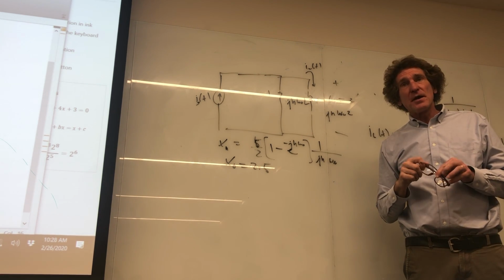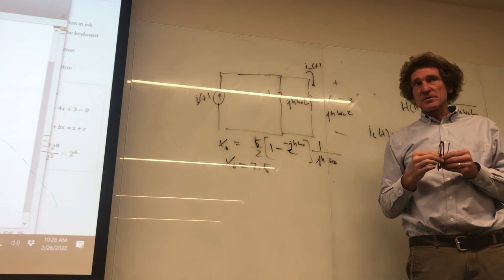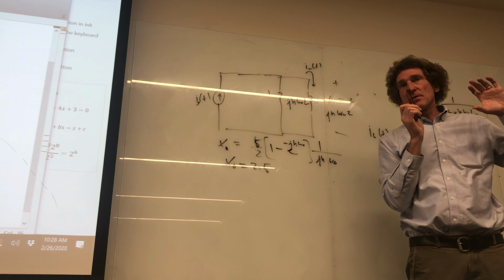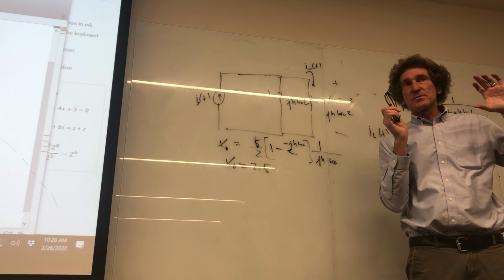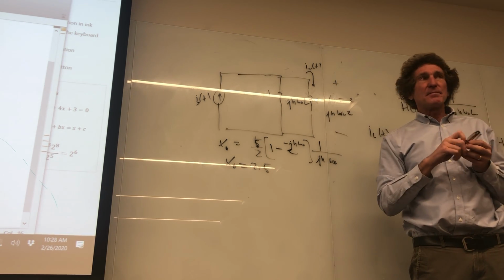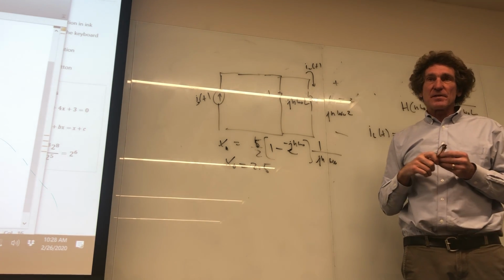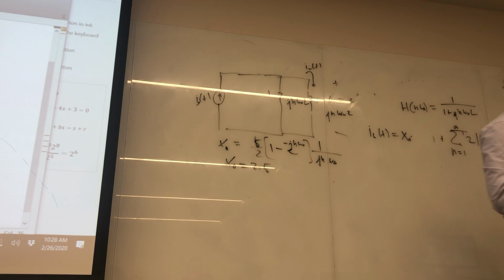You all know that, don't you? You can use capacitors or inductors. If you put inductors in series, it gets rid of ripple. Capacitors in parallel with the resistor will get rid of ripple as well. When I say ripple, the most common type that you run into is the 60 hertz that's annoying, so you can get rid of it that way. More on this later. All right, I wanted to get this to you.